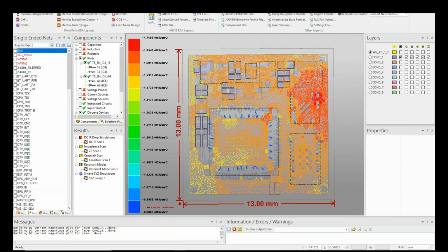One good thing about this tool is that it can automatically recognize the nets, single-ended, double-ended, differential, from the ECAD that you imported. And it can also recognize the components from your ECAD file. On the top, we're looking at the menu, and with the new 19 release, it's a ribbon style. I'll show you later.